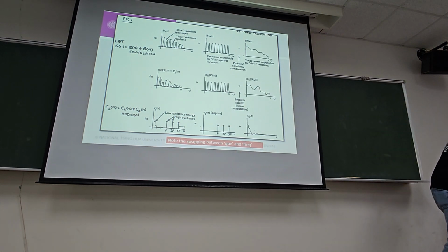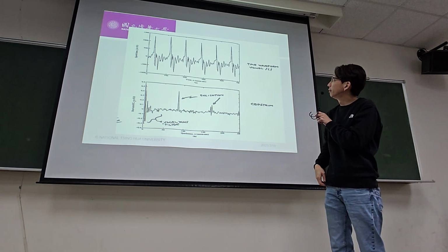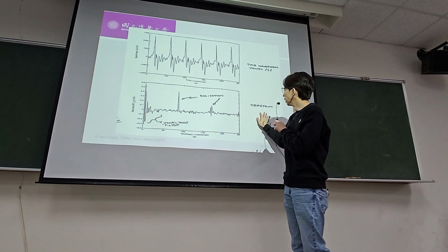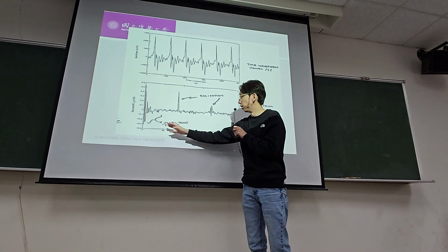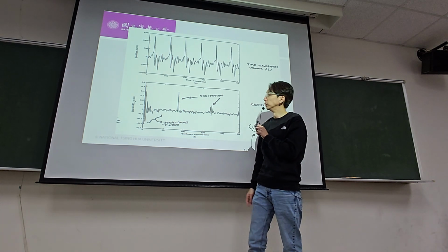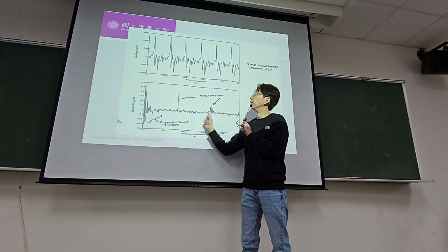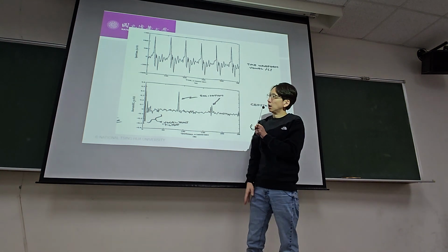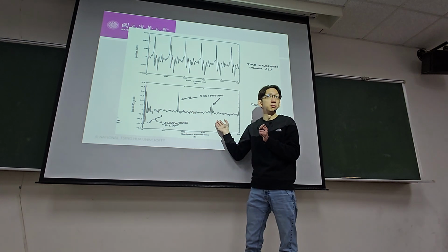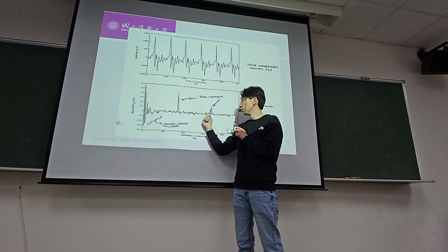Let's look at an actual real case here. This is the waveform of the vowel E. This is the cepstrum of this particular signal. Again you see the peaks approximately at the same places, the same periodicity as your signal. You can design a pitch extraction system on the cepstrum as well, because you see the clear peak here. You can do peak picking and try to find the differences.